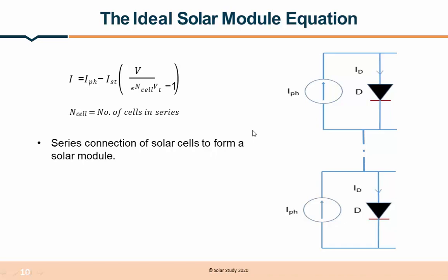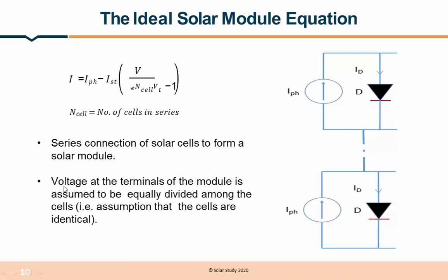So in order to make a module, I have to connect such a number of cells. The voltage at each cell is divided equally among the cells. Okay, like this, if I am getting some constant voltage around 36, each cell has the same voltage. How much? 0.6. Because for forward bias of the solar cell or ideal diode, the voltage required for conducting is 0.6 volt.